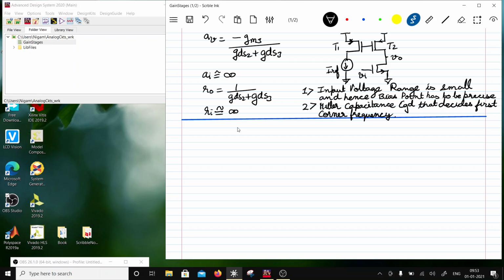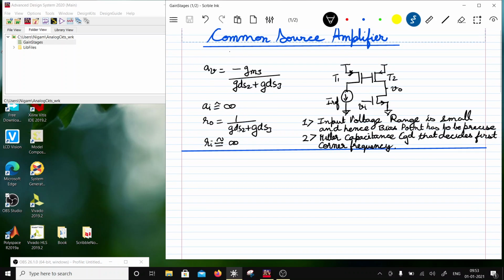And the very last thing is that you are going to have an output which is 180 degrees out of phase with the input. So in the Barkhausen criteria you have already lost 180 degrees, so that was a limitation.